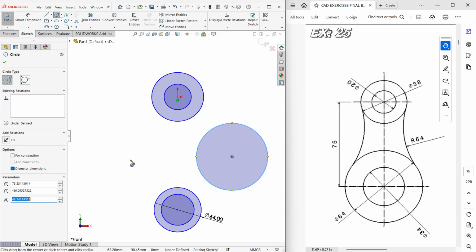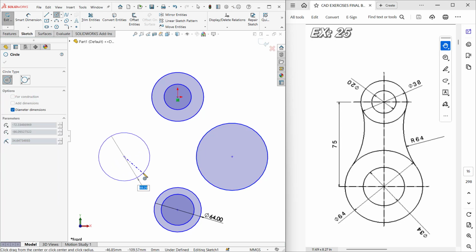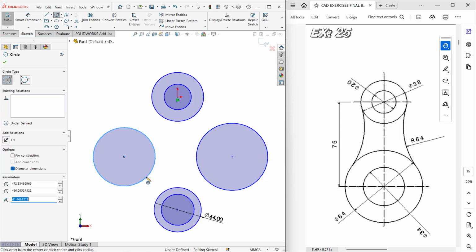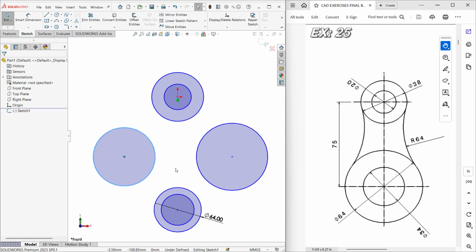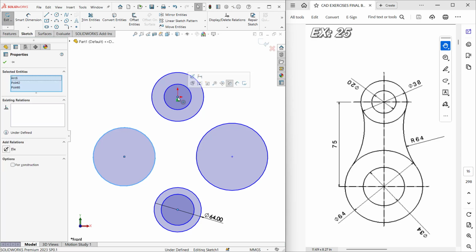And now once you're done with this, I do need to have the 2 tangency arcs here. So instead of drawing the arc, I'll draw a circle in short. I can even draw one more. If you want, you can even use the dynamic mirror tool, but right now let us have these circles here. Now you can see we have all the circles ready to complete the sketch. So next thing is I need to define the geometrical constraint, the third step in the sketcher workbench. Need to remember that.